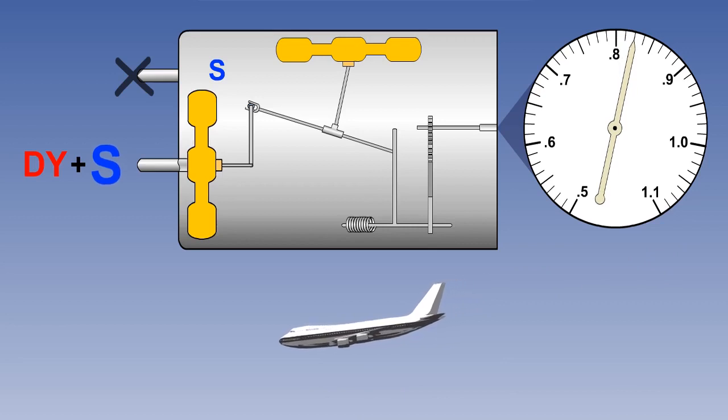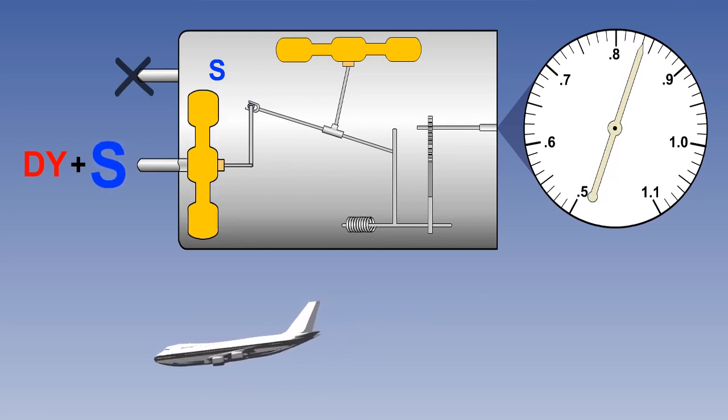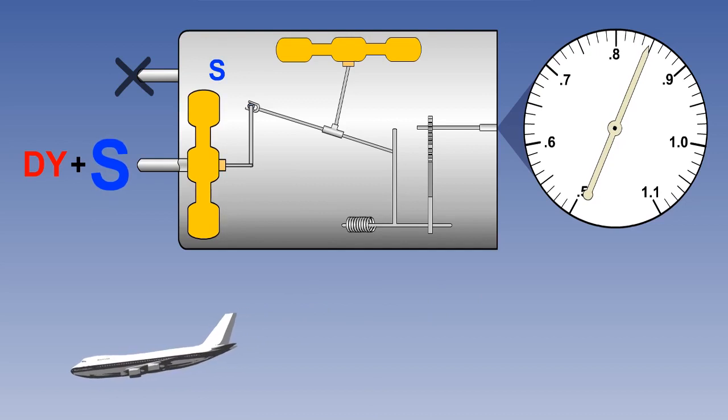However, the blockage prevents the static pressure from increasing within the instrument case, and provided the indicated airspeed remains constant, we can see that the expansion of the airspeed capsule will be excessive. Similarly, the reduced static pressure within the instrument case will allow the altitude capsule to remain expanded, causing the instrument to overread. In the climb, the reverse will happen, and the Machmeter will underread.